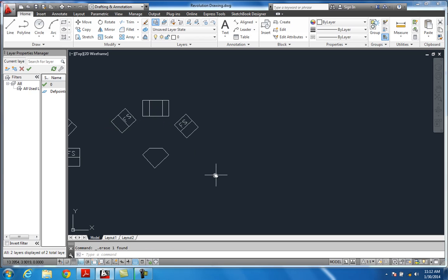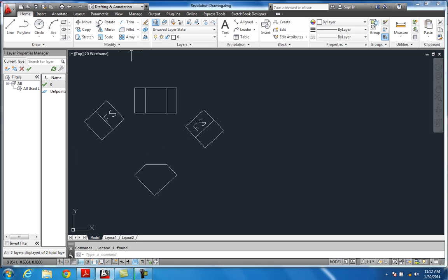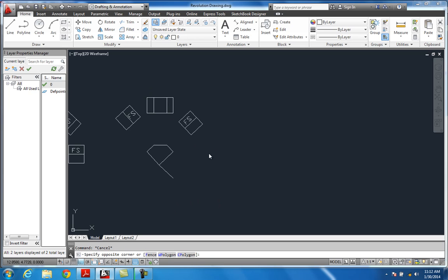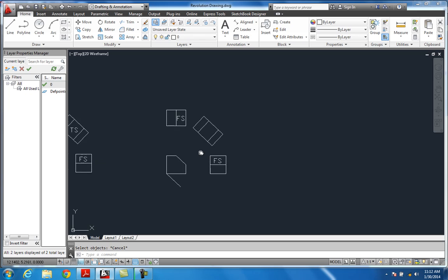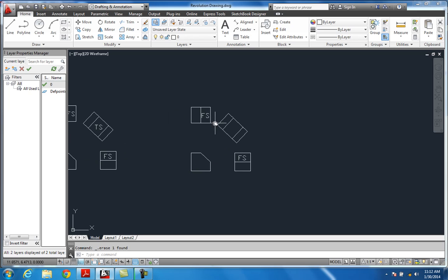Now at this point I'm going to delete that out. You've got that set up, and you can actually just revolve it back. To revolve it back, I do the same thing I did earlier. I just use a mirror. I grab, and see that's a complete polyline at that point. I'll just grab that and explode it. Do my mirror on this. Make sure my line's going across straight. And grab everything but that mirrored line that I just made. Rotate, grab that point, and come down here and catch the end point of it. Wow, that's as good as it gets.